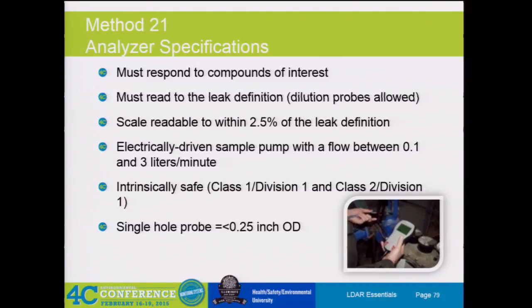So he had his regular probe tip, then he had the Tygon tubing tip, and then he added in another section because he didn't want to get that one dirty, and because he couldn't find any other tubing. So this tip was huge by the time we got out there. It was a little bit over 1/2 of an inch. If you looked at his leak rate results, he wasn't finding anything. And who would? You're sitting all the way out here, basically, trying to come in on a leak.